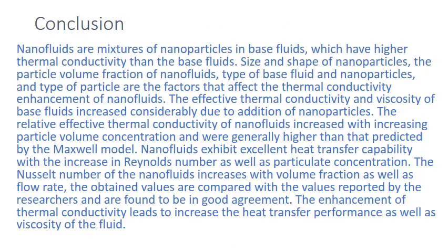Nanofluids are mixtures of nanoparticles in a base fluid, which have a higher thermal conductivity than the base fluid. The shape and size of the particle, the volume fraction of the nanofluid, the types of base fluid and nanoparticle are factors that affect the thermal conductivity enhancement of nanofluids. The effective thermal conductivity and viscosity of the base fluid increase considerably due to the addition of nanoparticles. The relative effective thermal conductivity of the nanofluid increases with increase in particle concentration and is generally higher than that predicted by the Maxwell model. Nanofluids exhibit excellent heat transfer capability with the increase in Reynolds number as well as particulate concentration. The Nusselt number of the nanofluid increases with volume fraction as well as the flow rate.